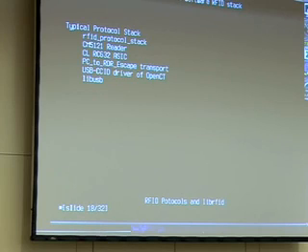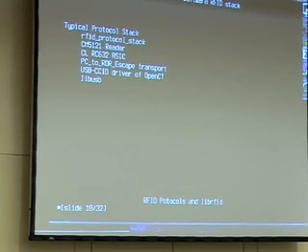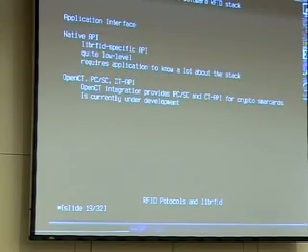So it's a contact-based reader, and that's why I'm using the CCID driver. So you can use the contact-based part of the reader first, and then on top of that there is some encapsulation for accessing the RFID part of the device, and then the CLRC632 ASIC, that's what Philips calls this ASIC in there, and the CM5121 reader object, and then the real protocol stack implementing the higher layer protocols on top of this.